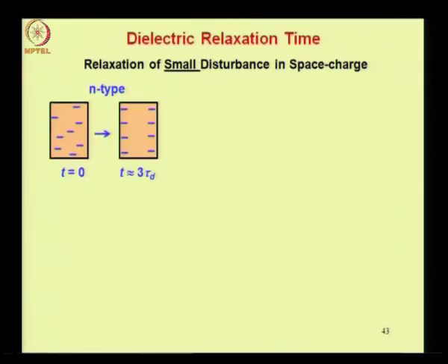We will also assume that the majority carriers that are injected are uniform throughout the volume. So in this case for n-type semiconductor you have injected electrons. Now what is going to happen? So as shown here, the volume concentration of the excess electrons will decay to 0. So what is going to happen is the electrons are going to all move to the surface. Now since this is a one dimensional situation we are assuming, the electrons move to either the right surface or the left surface, right. So we are not shown any electrons on this horizontal surfaces because our situation is one dimensional.